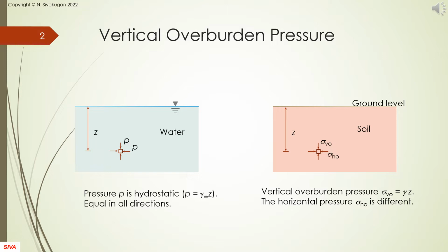Unlike water, the horizontal stress is not the same as the vertical stress in soils, in fact it is often much less. We will use the subscripts V and H to denote vertical and horizontal stresses. We will discuss only the vertical stresses for now.